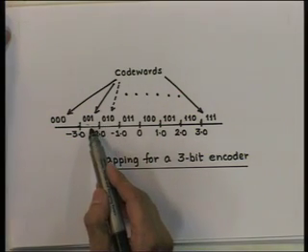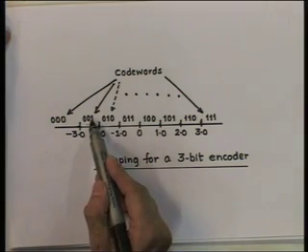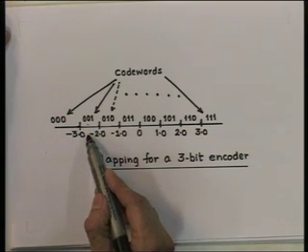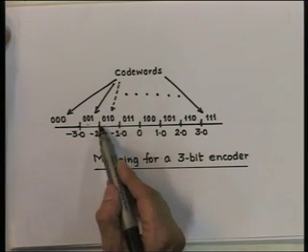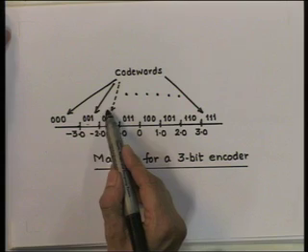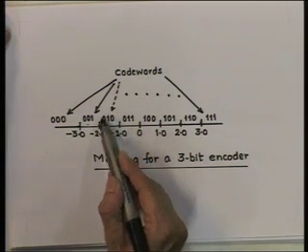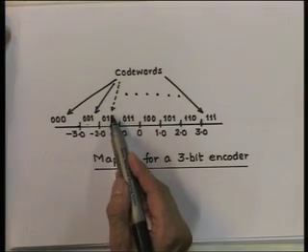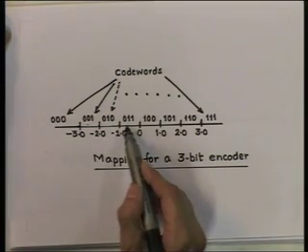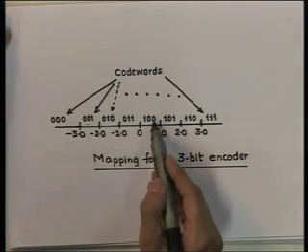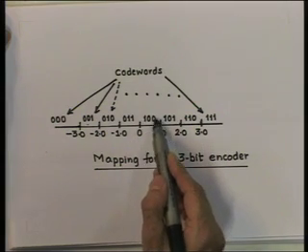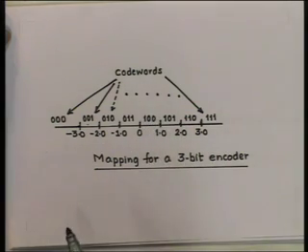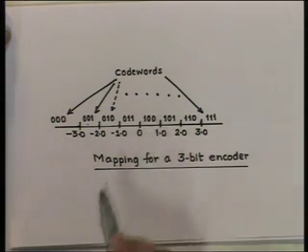The encoder represents all the source outputs that fall into a particular interval by the code word representing that interval. Now, as there could be many, possibly infinitely many distinct sample values that can fall in any given interval, the encoder mapping is irreversible.